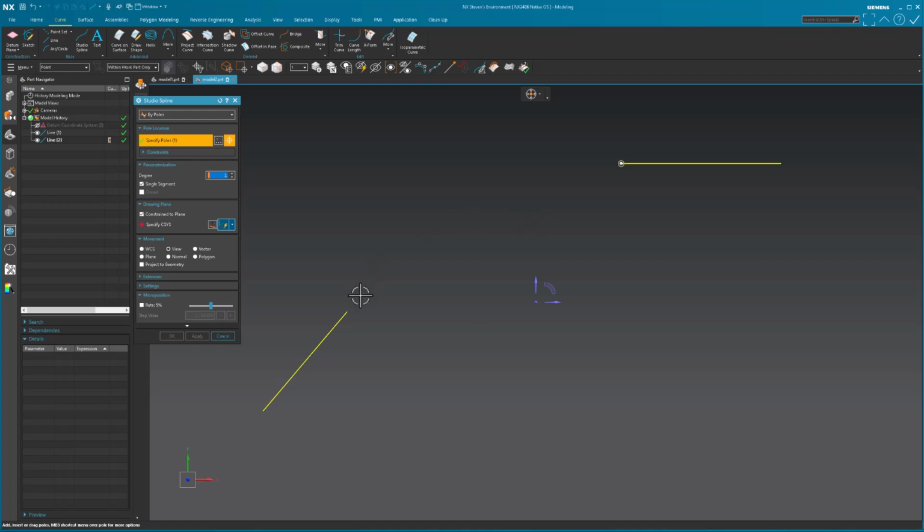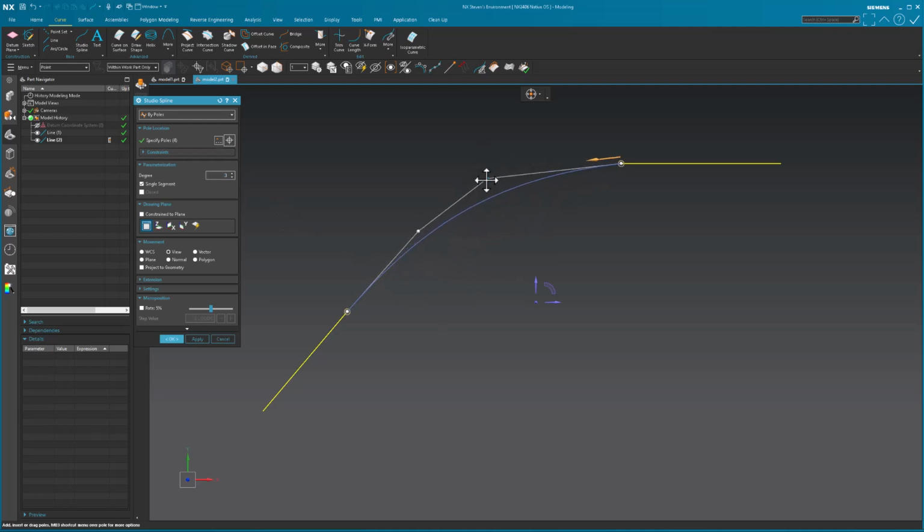And then if I come over here, I'm not going to change the math or anything. We turn that off, and there's my spline. It's basically 2 points. I talked about this in other videos recently. Now, if I come in after I've created it and start cranking up control points, between the end point, which is my anchor, and this middle control vertex, this acts as the vector direction. That's all this is. It's the vector.